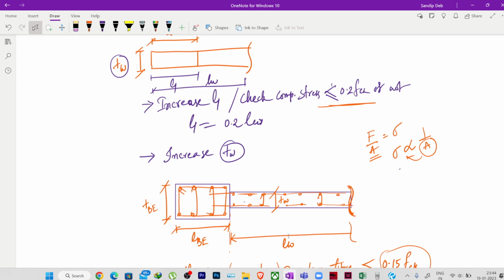So what we do in case of Mivan construction, we cast the whole floor together, including the slab, beam, column, walls, whatever it is. And in Mivan construction, it is not compulsory that you have to make your infill walls or partition walls as concrete itself only.